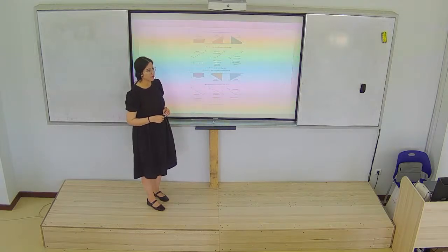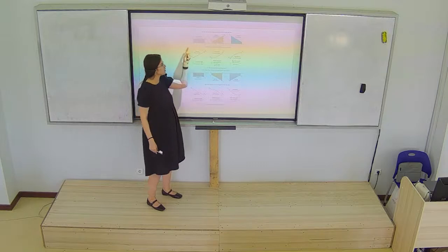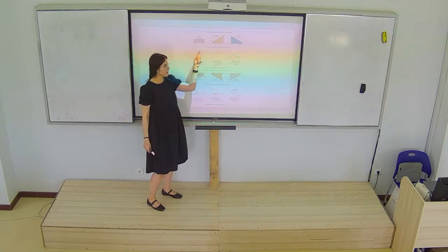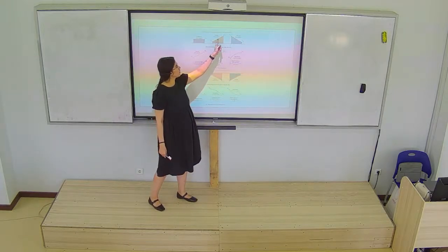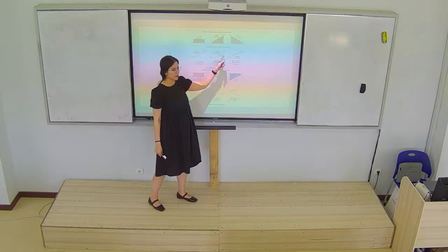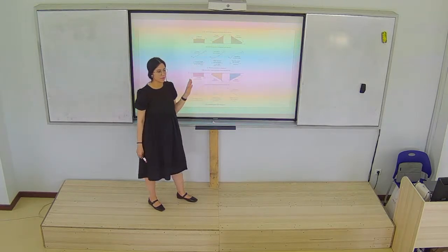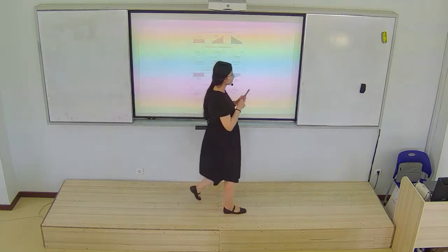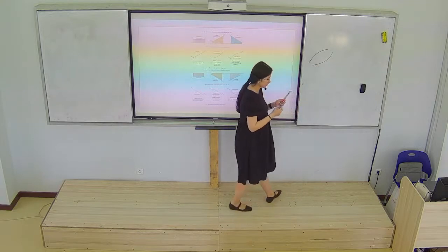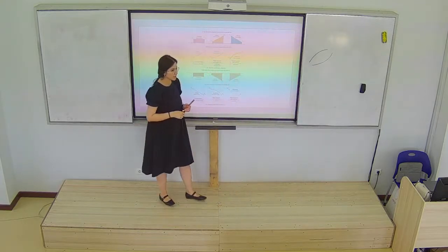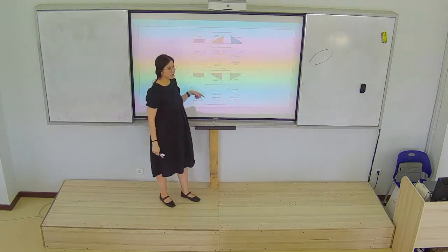If we have a distributed force, it means that the shear force diagram will be linear and our moment diagram will be parabolic. We have a condition: a parabola can be written like this or like that. That's why you are given two different conditions.